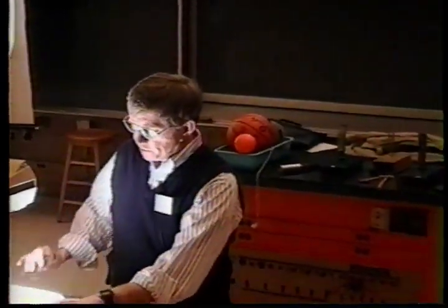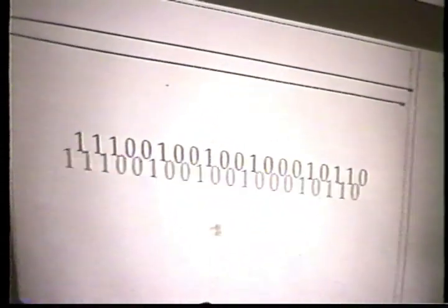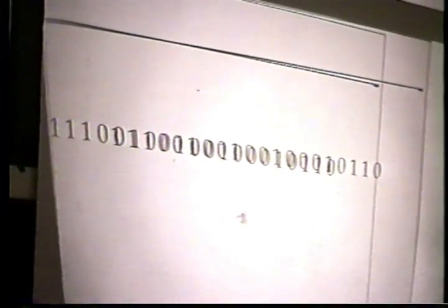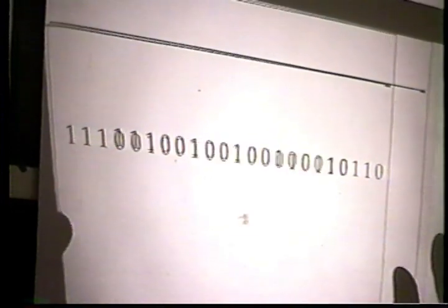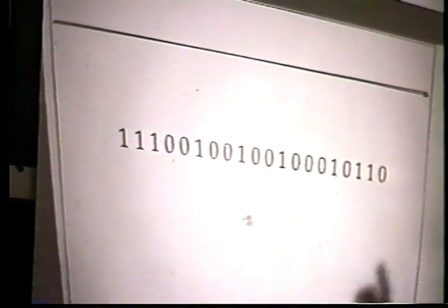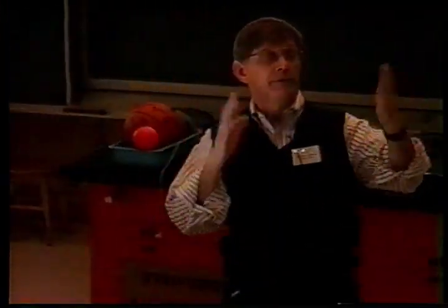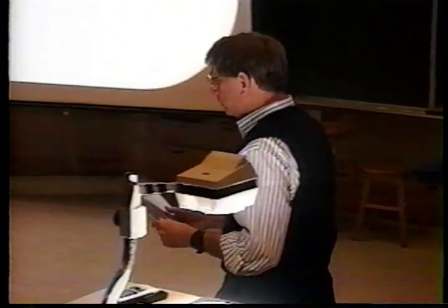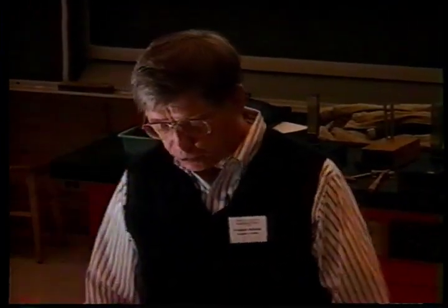So here it is a pseudo-random code, and here's the same one. One is generated by this unit, the other is received by it from the satellite upstairs. And as you slide this over this, at some point, bingo, they line up at the right time delay. And so you say, aha, that's the delta t, the time difference of arrival. Because that's how you measure it. And you do that for the 4 satellites, and then you're off in business. So that's called an autocorrelation function. You compare a signal to a carbon copy of itself. So that generates the pseudo-random codes for all of the satellites in the system.